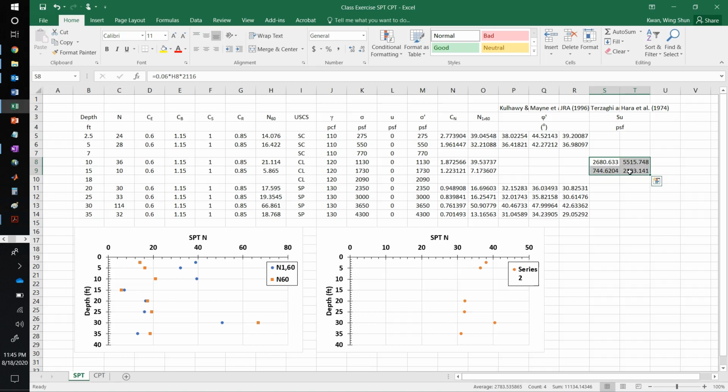I just want to give an idea what type of soils or what type of strength I'm getting, with the understanding that this is not reliable. And if I have the budget, then I will collect soil samples to do a compaction test or triaxial test in the lab to get a more reliable shear strength for clay